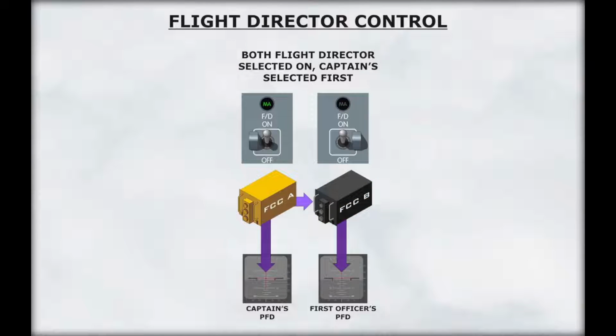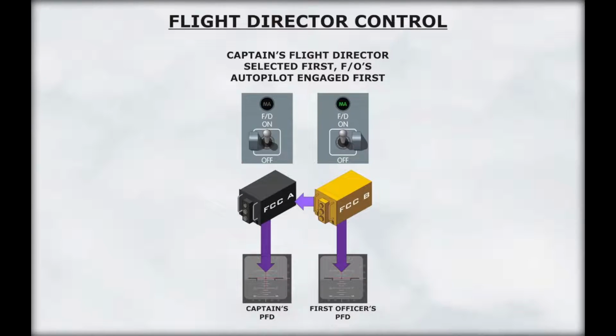If neither autopilot is engaged in the command mode, the first flight director that is turned on will make its associated FCC the master. If either autopilot is engaged, the FCC associated with the first autopilot engaged becomes the master, regardless of which flight director was turned on first.